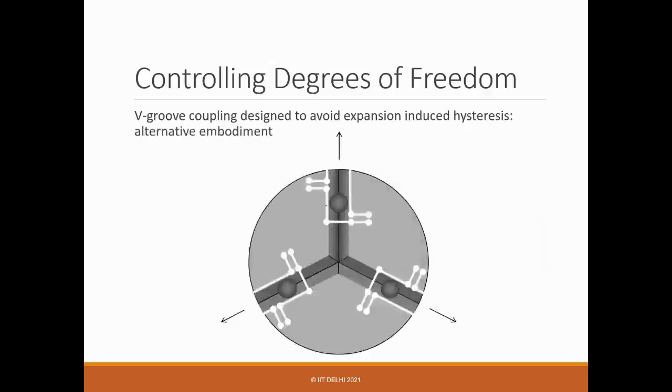Another solution is, you get this kind of, so this is like a shuttle. So you put in a flexure stage. So one bar here, and then you have a V. So another bar here. So this provides a parallel movement. So radial movement is allowed in individual cases. So a small adjustment it can do, and it will take care of any frictional stuff. So you can easily get rid of the hysteresis part.